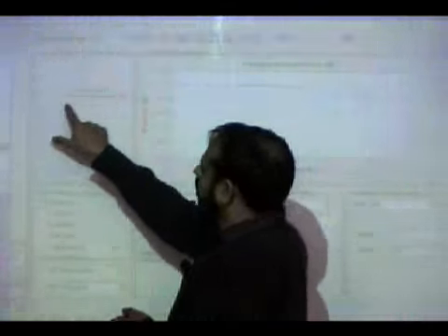So MATLAB basically designs a system, and design means it gives you B's and A's, the coefficients B's and A's, and also tells you the order. 31 means it is using 31 previous values, y n minus 1, n minus 2, n minus 3, till n minus 31. So if you actually want to go and read these values, B's and A's, you can do that. These are B's and A's.